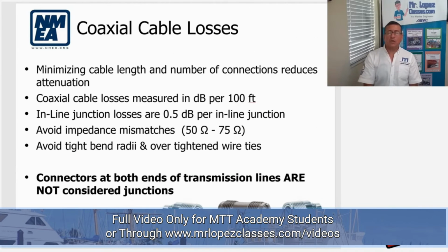The coaxial cable loss. This is the most critical part of the coaxial cable. Depending on the coaxial cable selected and the coaxial cable connector, you have more loss or less loss. But in general terms, in order to minimize the loss of the cable, you should select the proper terminal, and you need to select the proper procedure to crimp it or solder the terminal onto the cable.